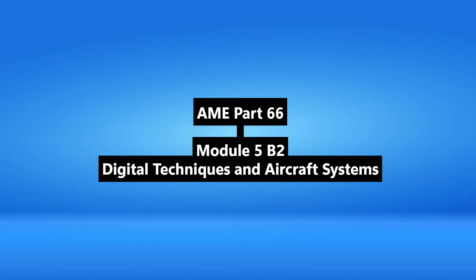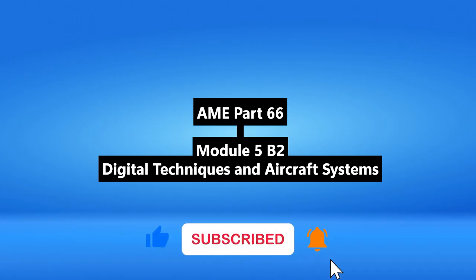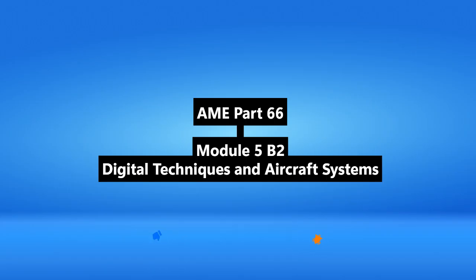Got it. And EMC versus EMI. EMC, electromagnetic compatibility, is the goal. It means a piece of equipment works properly in its environment without causing interference to other things, controlling its emissions, and without being disrupted by interference from other things, having sufficient susceptibility or immunity. EMI, electromagnetic interference, is the problem, the unwanted energy causing the disruption. What about HIRF, high-intensity radiated fields? Sounds serious.